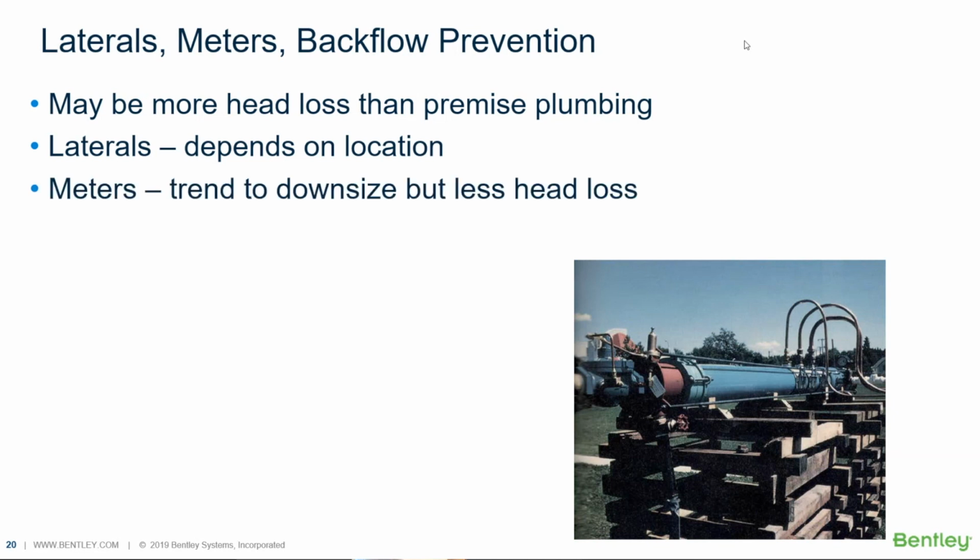Now, metering is becoming interesting because as research is being done, we have the water demand calculator and such. We see that we could downsize a lot of meters. A lot of meters are oversized in water systems these days. But when you downsize them, you're including extra head loss. So you've got to be able to account for that when you're looking at the system.